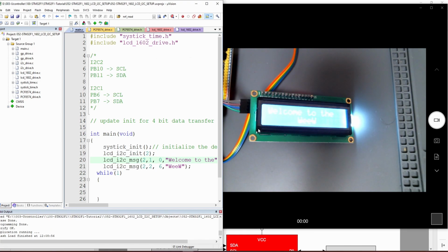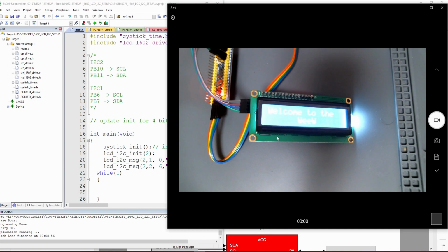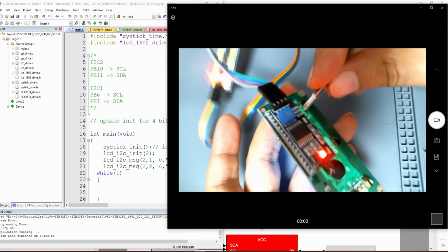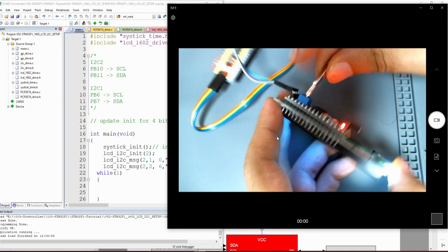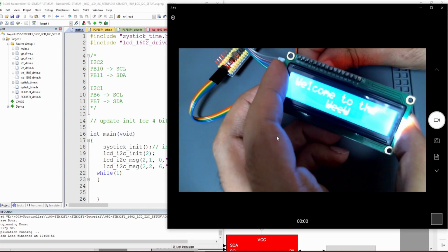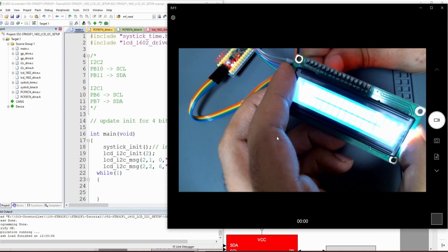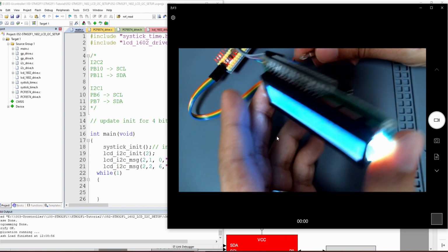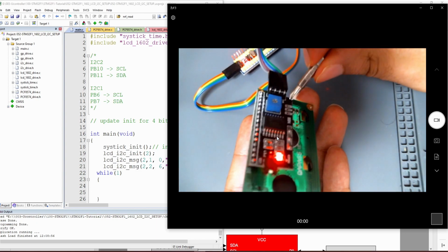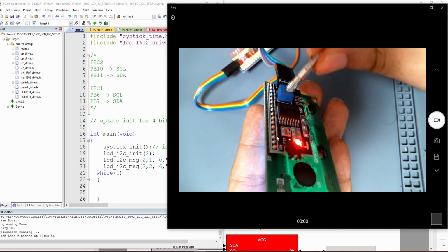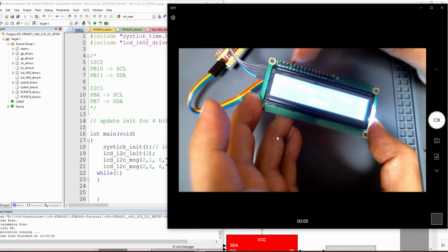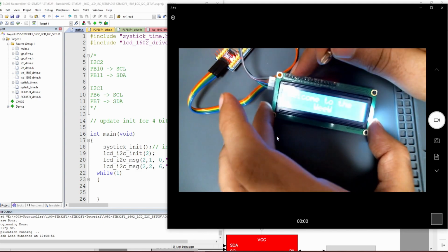So you can see it's really quick and straightforward. Just one thing for you guys, you may not see anything, and this is because of the potentiometer that you have here. So I will start turning it a little bit, and you will see it may disappear. So you may take a look and check what is going on there. You have to play a little bit with this potentiometer here that we described in the function to check, maybe the display contrast is not good.